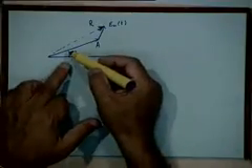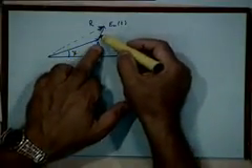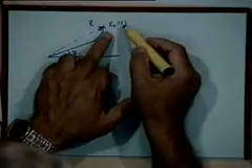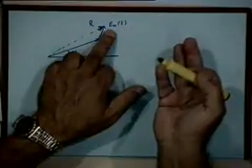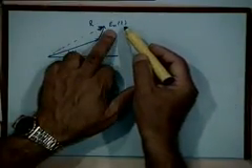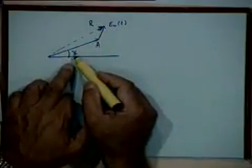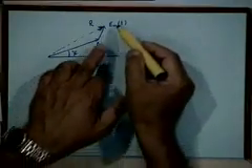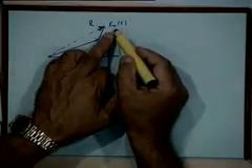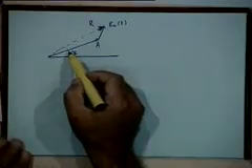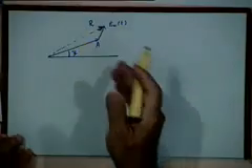So the rate of variation of psi is much slower than the rate of variation of angle and amplitude of E_n, because of the bandwidth. We have used this argument earlier; it is not a new argument. The bandwidth of psi is the bandwidth of the message signal m(t) itself, B, while that of the noise is 2 delta f plus B, or delta f plus B at the baseband level. So this fluctuates much more rapidly. That is why we could make the assumption last time that psi is nearly constant while this is fluctuating, and we did the short term analysis.